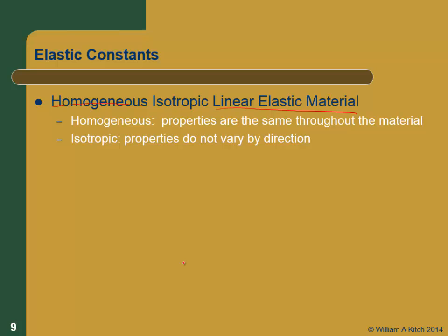So like wood might be homogeneous but not isotropic because it's got grain and stuff. Soil is often, I mean, the simplest model of soil is homogeneous and isotropic, and we use that a lot. But really, soils are often layered in the horizontal direction due to deposition, and then they could be homogeneous but anisotropic. So aniso, let me write that one. If you put an 'an' in front of this, it means it's not the same in both directions.